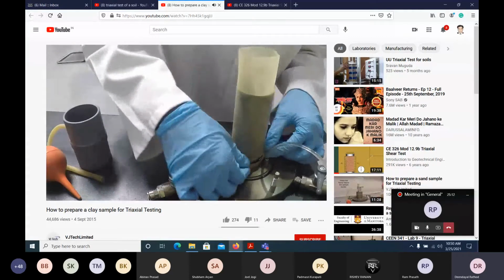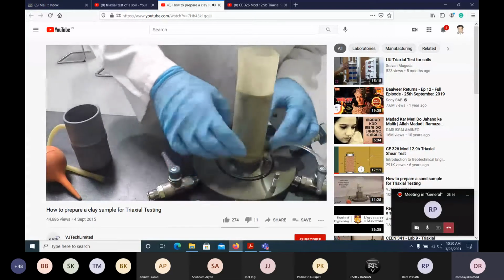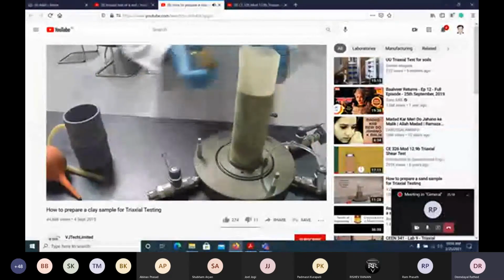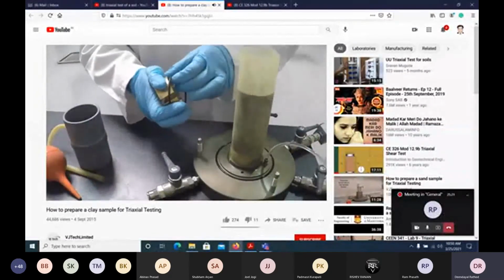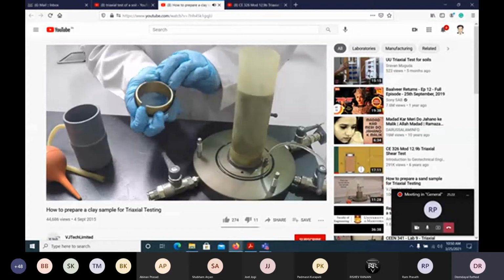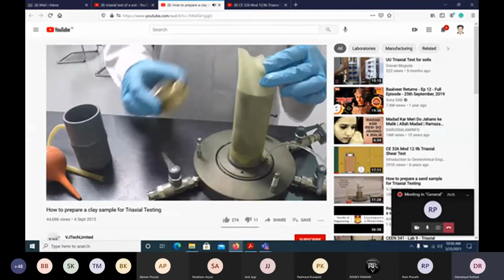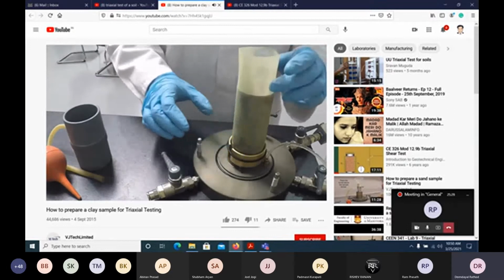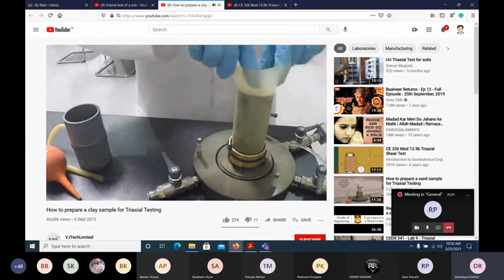In some cases, you may wish to add a secondary O-ring to ensure the membrane is completely sealed. Another O-ring is required to secure the top of the membrane. Stretch another O-ring over the stretcher and place it on the specimen. You will need to do this before you put on the top cap.